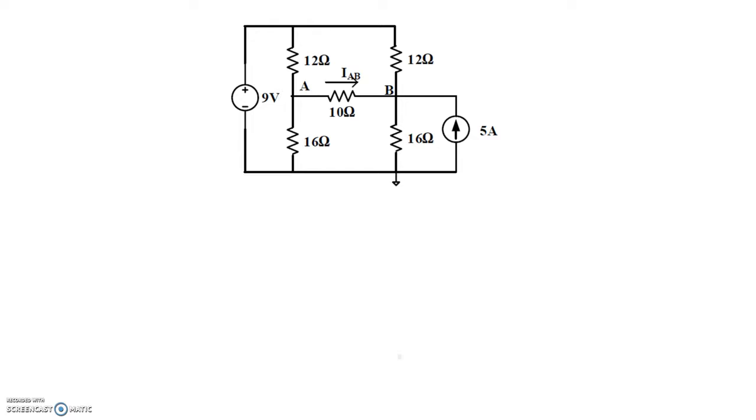Let's start out by arbitrarily defining a number of currents that flow through the different resistors. I'll call those I1, I2, I3, and I4. So I have I1, I2, I3, I4 labeled. Now we have a reference node given down at the bottom. That's a ground node, so that's a reference node. Because that is ground, and there's a 9-volt source right here, we can immediately say that this side of the voltage source is at 9 volts with respect to that reference. So this top portion, all of that is going to be equal to 9 volts.